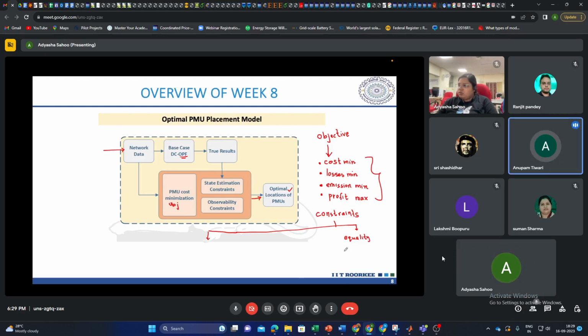Load. Always a load. Yes, we have to match the demand load. So generation is equal to demand is the equality constraint. True. So sum of the generation from the generators should be the total load that is being served, plus sometimes if you consider the loss also, but sometimes you also neglect this. So this will be our equality constraint for power system.